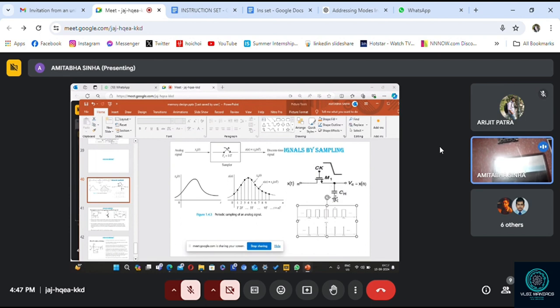So there is a capacitor. What is the function of this capacitor? To hold the value, hold the charge. The charge will be stored and this value will be held in the capacitor. I can assume that this capacitor is basically a storage unit which is storing the charge at that point, that is, the equivalent value at a particular n will be stored. But before the next value comes, this capacitor has to be discharged. Isn't it?